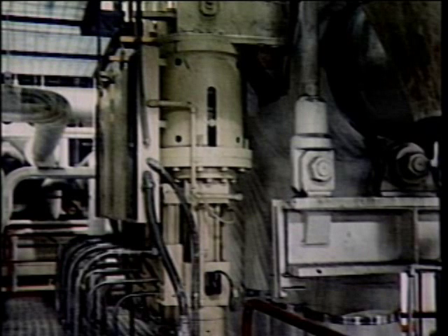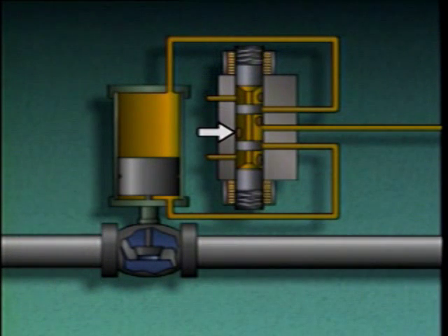Two problems commonly associated with hydraulic actuators are contamination of the hydraulic fluid and hydraulic fluid leaks. Hydraulic fluid can become contaminated with dirt, water, or other foreign substances. Some contaminants can corrode the actuator and cause the piston to stick inside the cylinder, affecting the positioning of the valve. Contaminants could also collect inside the pilot valve and prevent the pilot valve spool from shifting correctly.